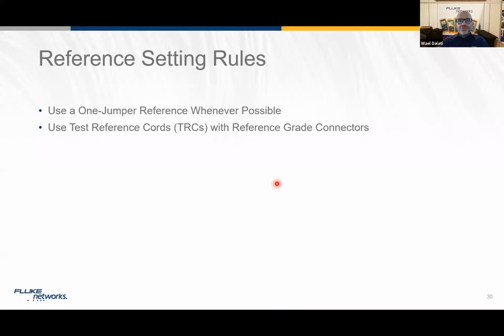And what do we need to do in preparing our testing for fiber optics, particularly in optical loss measurement? If I read the two codes, that's why this slide is purely focusing on two lines, the standard requirement. You need to use what we call the one jumper method or one cord method, and we need to use test reference cords. The test reference cords are, by definition, not the standard patch cord that you bring out of your installs on your site when you open the box.